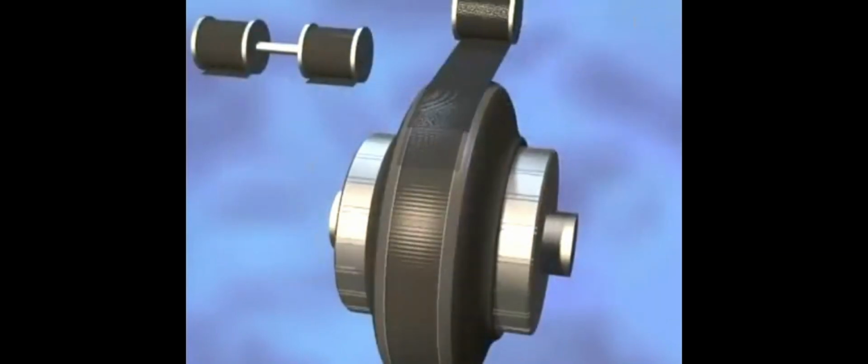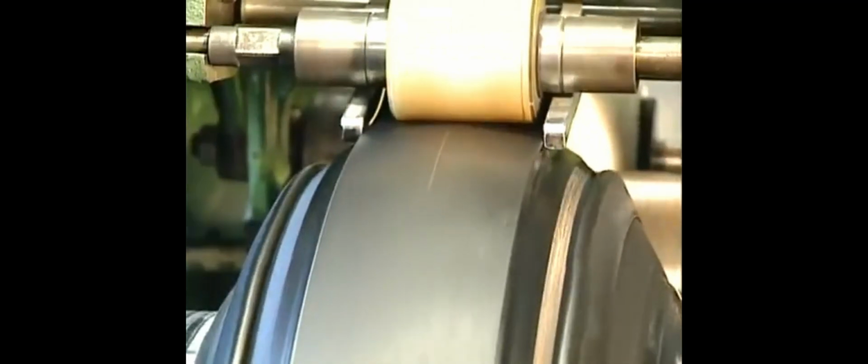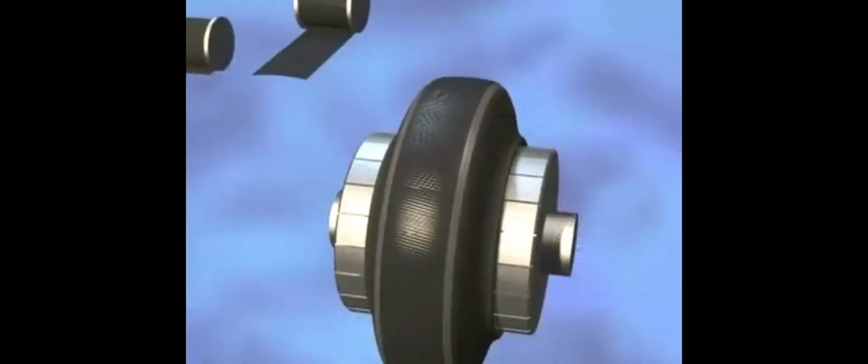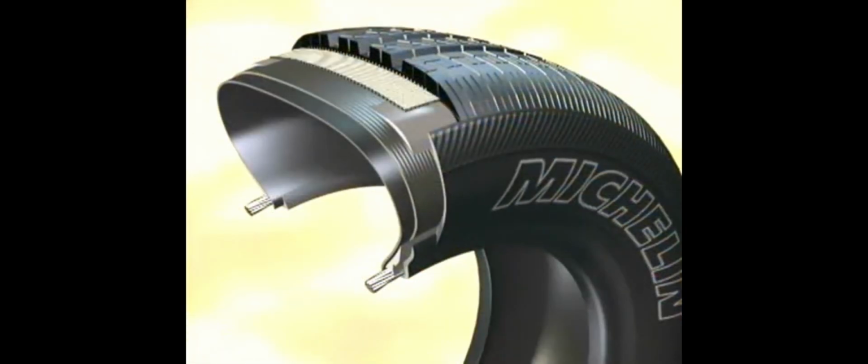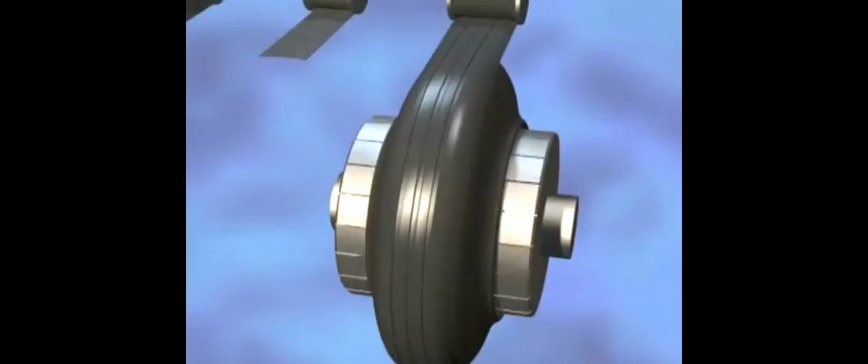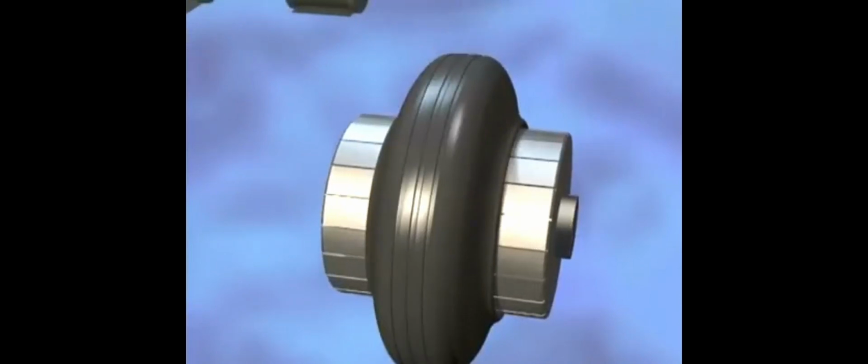The reinforcing tread plies providing directional stability and mechanical resistance have yet to be added. Fine but highly resistant steel cord strengthens these plies. Being laid crosswise to the casing ply, it forms shape-retaining triangles. Now it's time to lay down the tread rubber. It is this part of the tire which will have a tread pattern and will be in contact with the road surface.